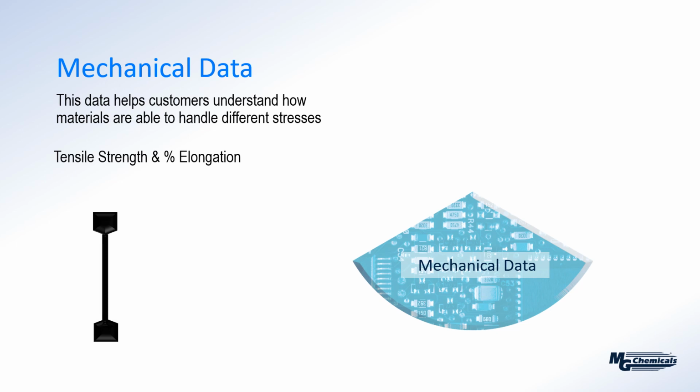So the first one I want to draw your attention to is the tensile strength and percent elongation. With this test, we make a specimen that is nicknamed a dog bone. And you see it's a very thin section in the center with two ends. What we do is we place those ends in vice grips and secure it very firmly. Once it's secured, we put it in a machine that's going to try and tear that sample apart. So we hit play, and these vice grips start to pull in opposite directions, and eventually the material will expand and start to give.